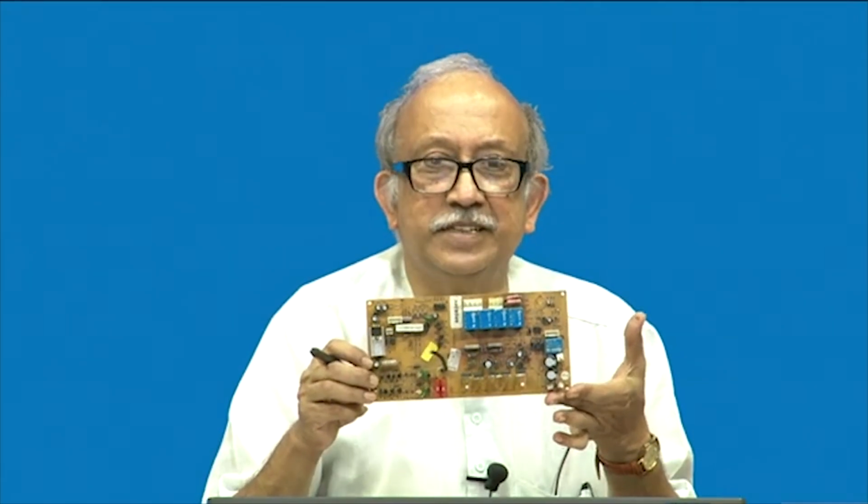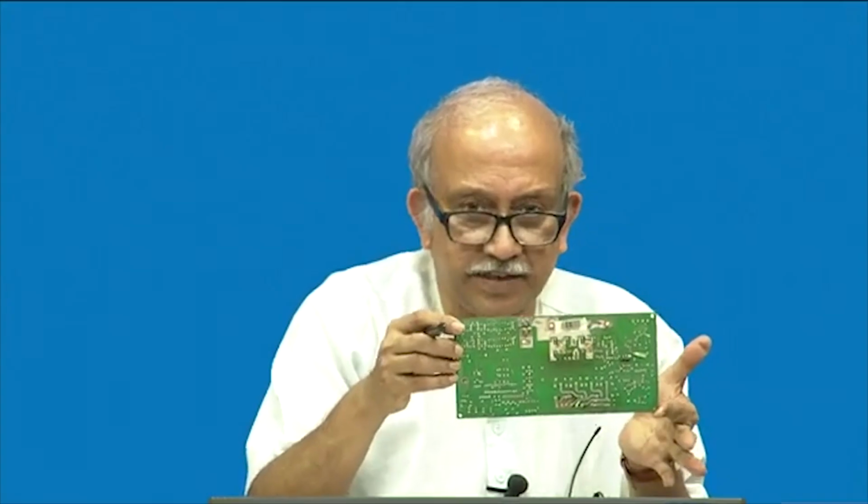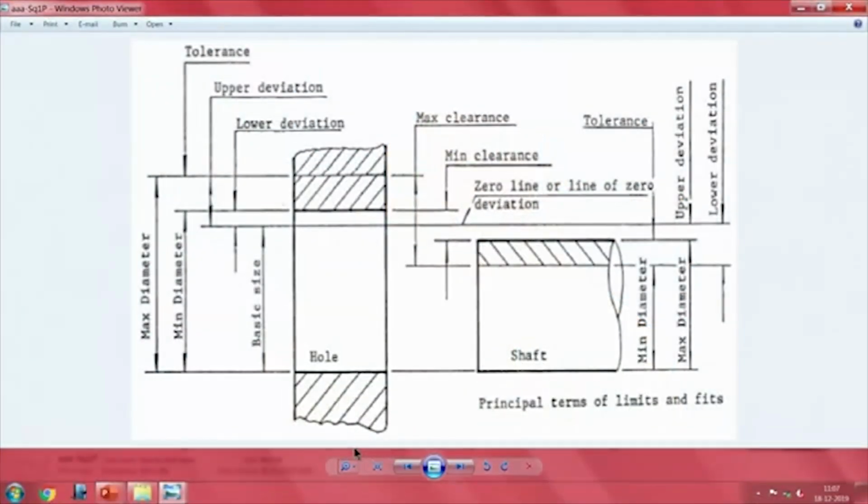shape, all these have to be considered, and very peculiarly, probably involving soldering, probably involving shrinkage, involving wicking and wetting of the various solders, various types of thermal bridges as well as dams have been built inside. If you give a gap, heat will not be shared. If you just leave a solid copper area, in this case the current will be shared. So, these things are all to be considered when you are making anything which is bigger than a normal simple 1 amp circuit. Now, I will go on to, kindly see my monitor again here,